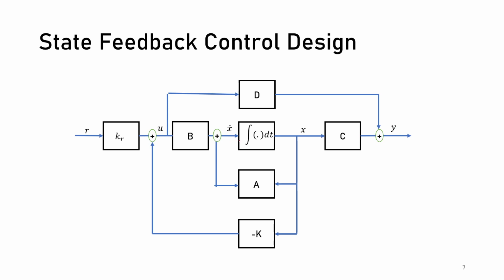Okay, so block diagram here. When you want to draw this, you start with the state equation. Start with H. When you have H dot, you just integrate. Actually you can also use 1 over S here, it's not a problem. You integrate, you get H. And you have H dot equal to AH plus BU, right?